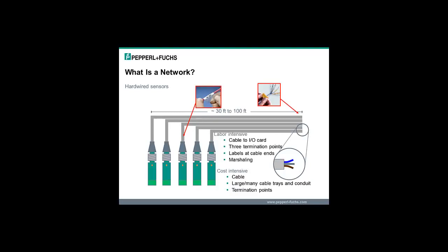Each cable lead must be stripped and possibly prepared using a ferrule. Every cable needs appropriate labeling, and since cables are usually not directly connected to the I/O cards but are marshaled via terminal strips, the number of enclosure terminations is even greater.